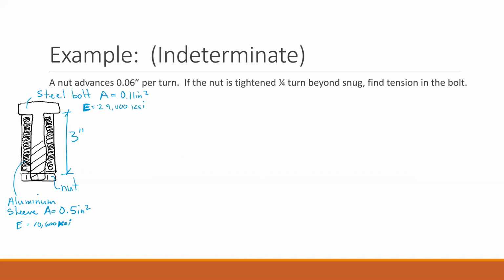So when I turn this all the way around, if I take this face and turn it 360 degrees, now it's back towards you, it actually moved upward on the bolt. And the amount of that upward movement has to do with the orientation of these threads. The more inclined the threads are, the more that nut is going to move up the bolt for each turn.